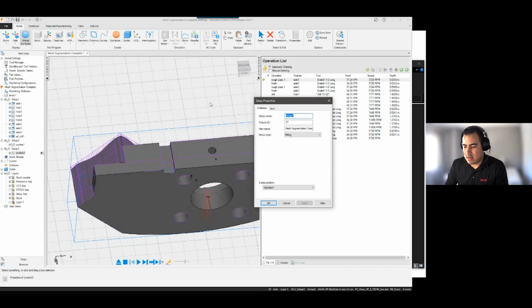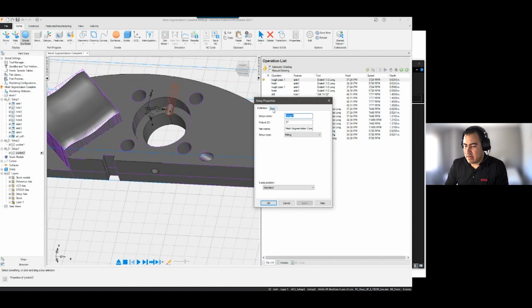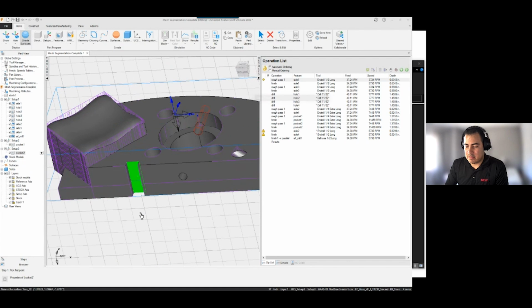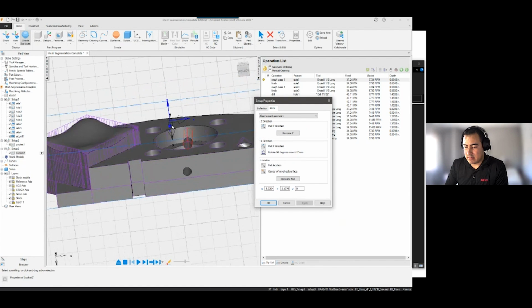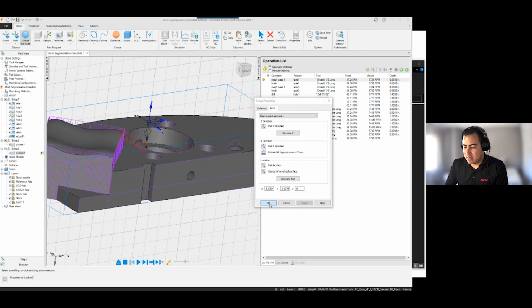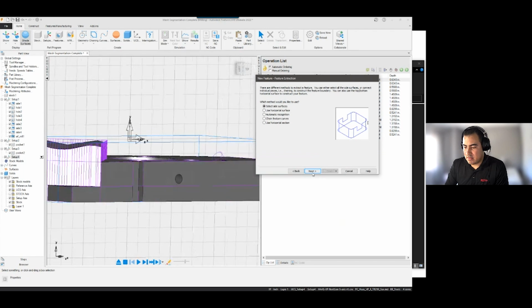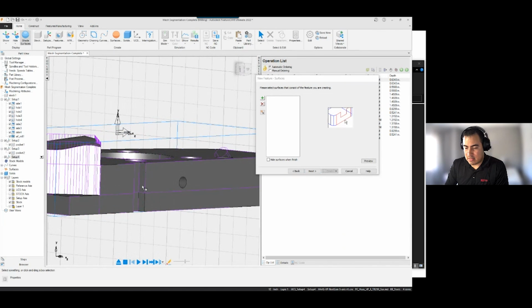So I'm going to go ahead and go to setup. Once again, define the 0, make sure it's off the center, align to part geometry, right? And then we're going to go ahead and pick our Z direction. It looks like it's in the correct orientation there. So we're going to say okay there. Once again, a feature, this is going to be a side. We're going to extract that with feature recognition. And then just select our surfaces.